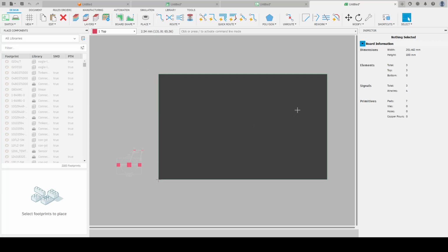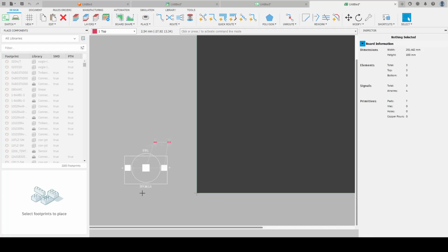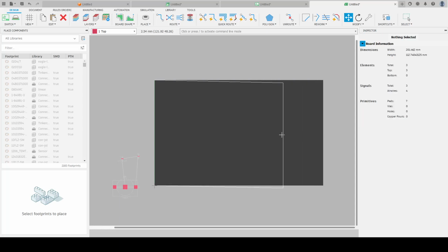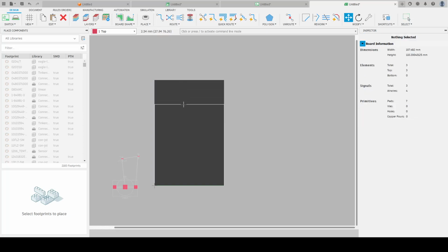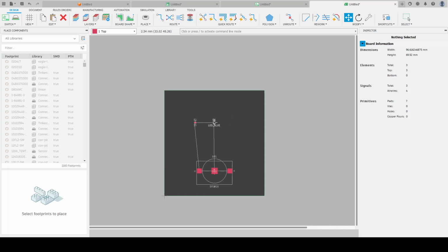Okay. So this is the physical board. And our components are placed outside here. So we can actually arrange them a bit before we place them on, but see that the board is a bit too big. So what we can do is we can move it. Let's just move it like this. Not gonna do a lot here, but just to show how you do that. And then you just simply drag your components over. You can zoom in a bit. Do like this. Like this.